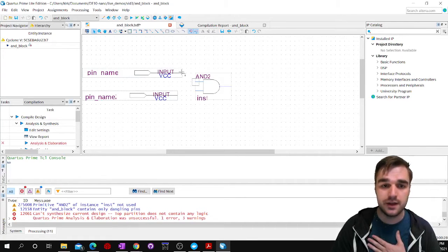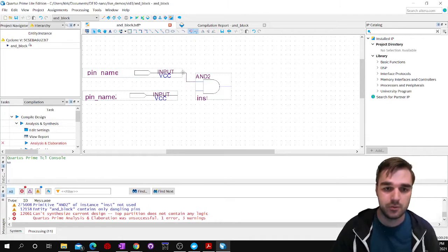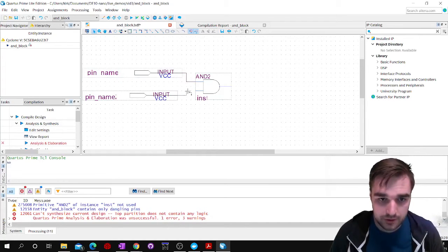What I'd like to do instead is kind of just come out this way and line it up so I could go straight in, but it'll only draw one angle on this wire until I let go. So I'll let go, and now this wire is incomplete, but it's stretching out, and then I'll click over here and I'll drag it the rest of the way and connect it. So now it kind of does this snaking, and I think that makes it a lot more organized. Instead of just having one turn, we're doing two turns to get there. Anyways, so I'll click and drag, and I'll come over here, and then I'll connect this guy. And there we go, we just wired him up.